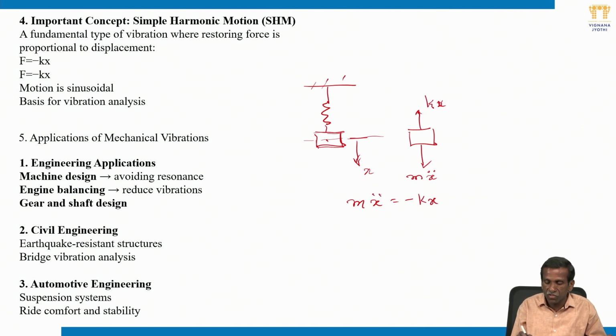This force which is going to be applied is equal to minus of restoring force. Direction is opposite, it does mean. Other way around, you can say that one principle is called D'Alembert's principle. Because acceleration of the body is downward because of given displacement, the inertia force acts upward, with magnitude equal to the acceleration force. These must be maintained in equilibrium. That means D'Alembert's principle tells that inertia force and restoring force of the body together, the algebraic sum of that is equal to 0.